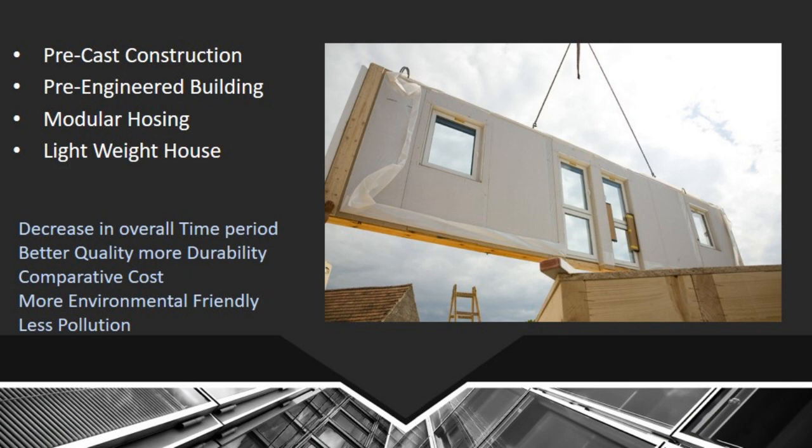For example, if you are going for a 3-story building, there would be 3 stages when you will need to have a halt of around 28 days if you are following good practice. But if the things are already cured, and they are following all the durability and strength parameters, then we are having a good product, and we are implementing it in such a way. That sort of technology can help us achieve good quality parameters also.